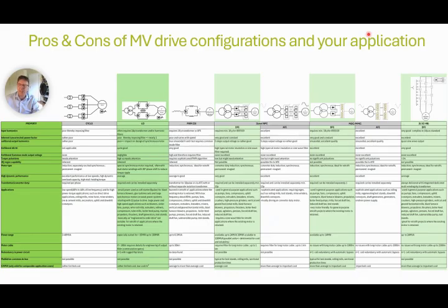A standard non-inverter rated motor requires a dU/dt filter or a sine wave filter in this case. The common mode voltage is only a real problem for the PWM CSI, and this drive will therefore always include a common mode filter.